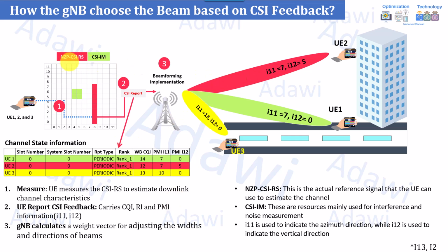And again, the non-zero power CSI-RS, as I mentioned before, is something controlled. You can even increase it to 32, so you will have more overhead here, but this also gives more advantage. The user can have more codebooks to select from, and it might also result in a wider beam. So as I highlighted before, there is always a trade-off between different configurations and so on.